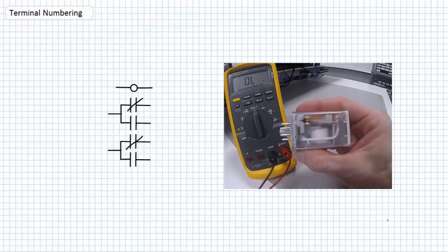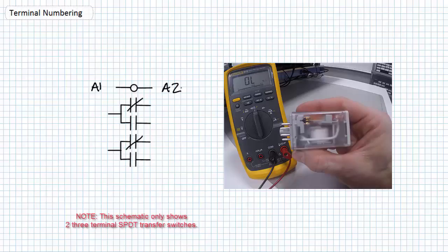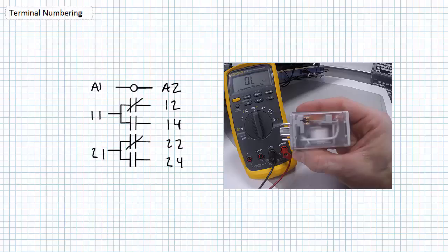Recall that control relays and contactors are characterized by a coil and associated contacts that switch their activated state when the magnetically linked coil is energized by pilot voltage. An 11-pin ice cube relay is ordinarily characterized by the coil from terminals A1 to A2 and 3 single-pole double-throw transfer switches where the first digit identifies the particular switch and the second digit identifies its deactivated state.